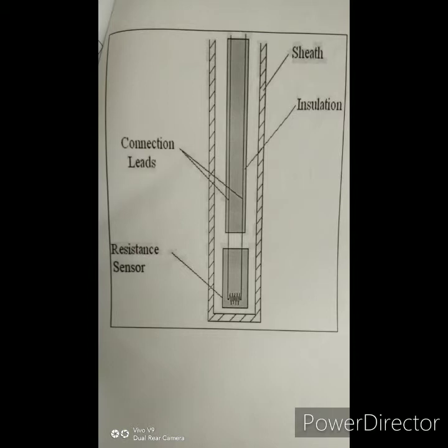Resistance temperature detectors (RTD). A commonly used temperature sensor is the resistance temperature detector, also known as resistance thermometer. Unlike filled system thermometers, the RTD provides an electrical means of temperature measurement, thus making it more convenient for use with a computerized system. An RTD utilizes the relationship between electrical resistance and temperature, which may either be linear or non-linear. RTDs are traditionally used for their high accuracy and precision.